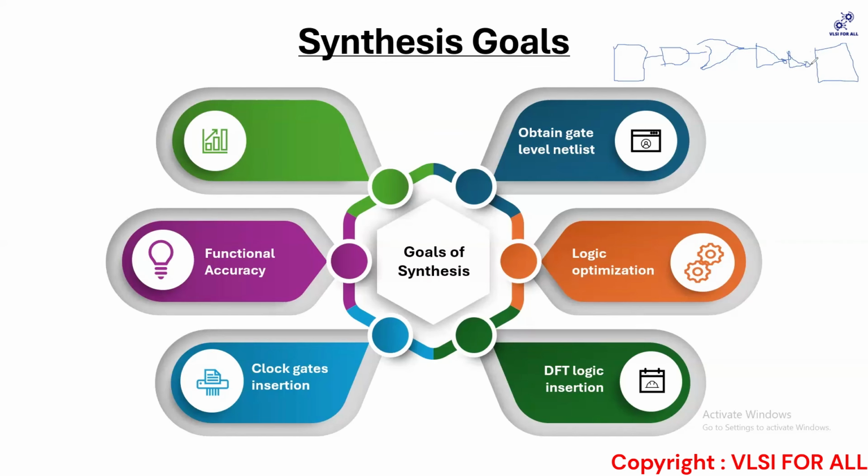Now, for example, you opened up a design manually and thought, I will try to optimize it. You were doing some primary timing checks to see whether I can change this inverter, increase its drive strength, and check whether my path is being met or not. Let us say you replace this inverter with a buffer. Let's say the input over here was 1.